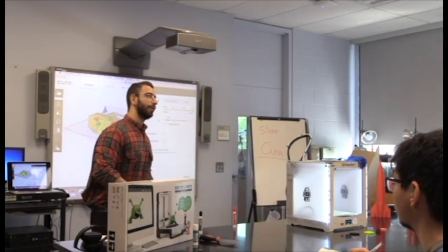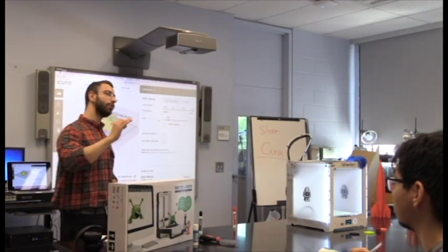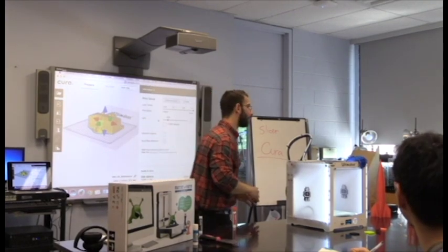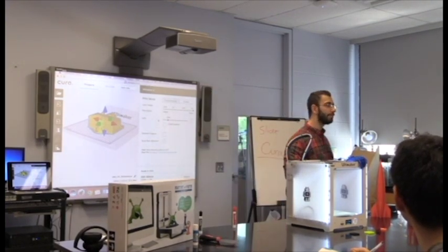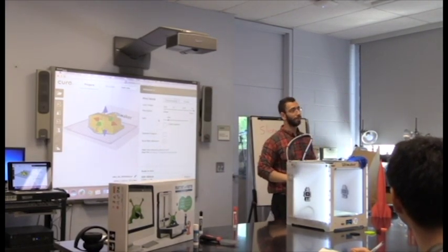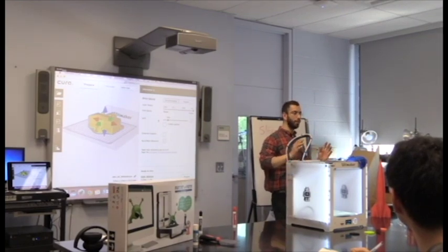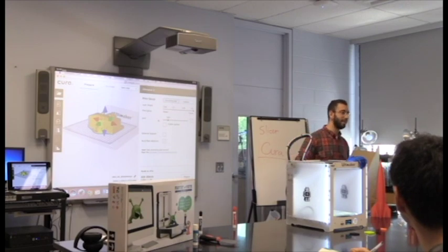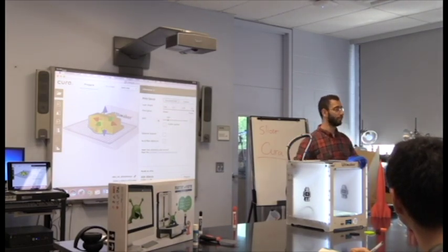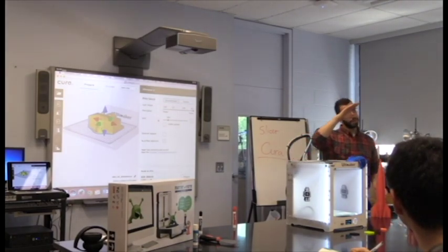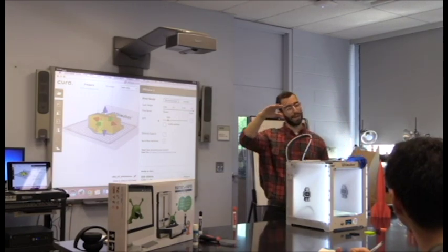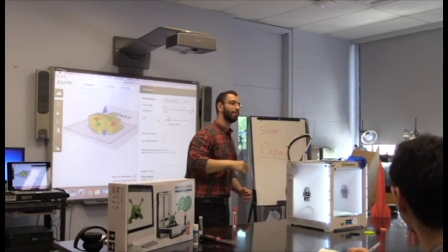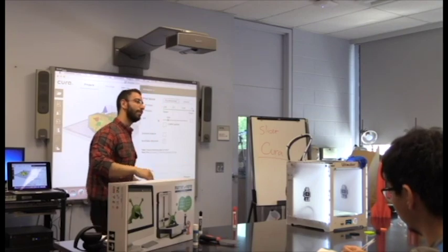Sure, you're probably right, but it gets to a point where usually right about 30, max 50% infill is as much as you want. That will almost provide nothing more. The other 50% will provide nothing but more time and almost no strength. So right about 30% is where the curve starts to flatten when it comes to strength. Okay, does that make sense a little bit?